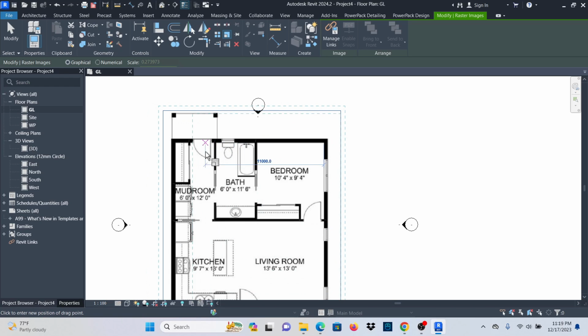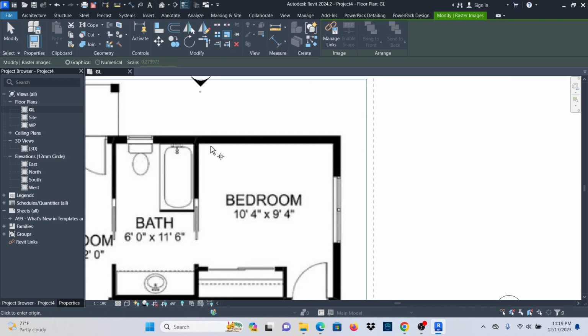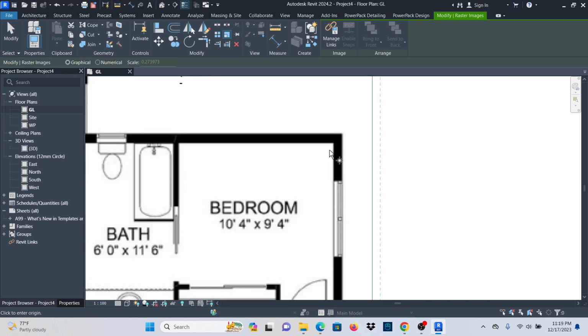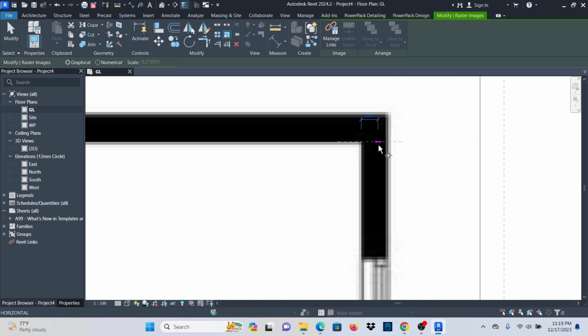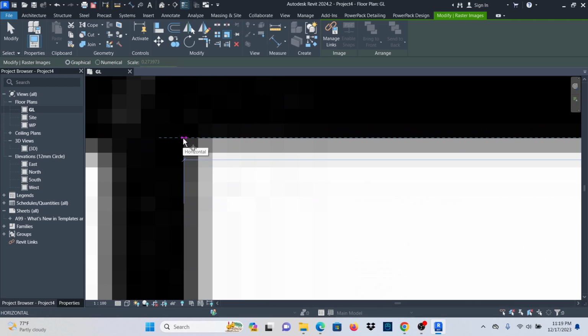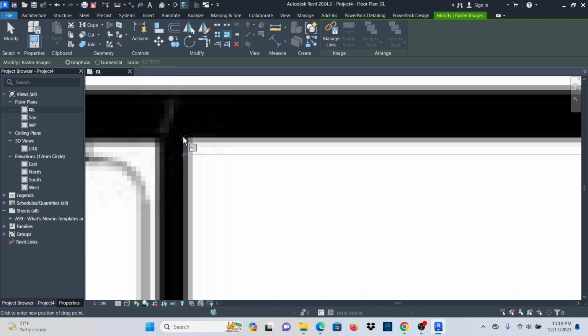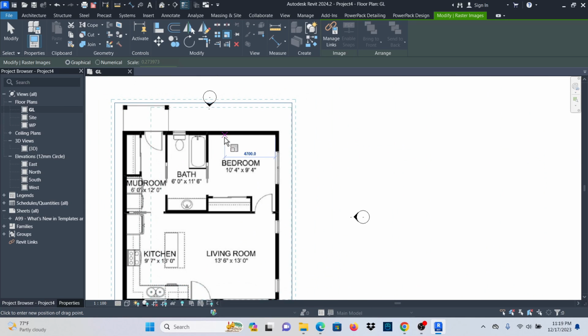Now, actually, if I want to scale the overall dimension, I can do that. I'll just escape on my keyboard once, go back to scale there, and now I'll pick the inner dimension so that I can scale to the correct dimension that I want. I'll pick the corners roughly somewhere there, and now pick also the inner one somewhere there. You see that is 6.2. And you see that it scales like that.